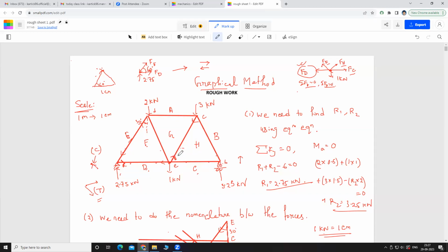Means actually you need only two unknowns because you have two equations. So that is the condition. For a point, you need to check how many unknowns are there. If it is more than two, then you can't do it at that time. First of all, you need to check at the points where we have two or one unknown. So at this one, if you do, these two members are done. So 1, 2, 3, 4, 5, 6 done.